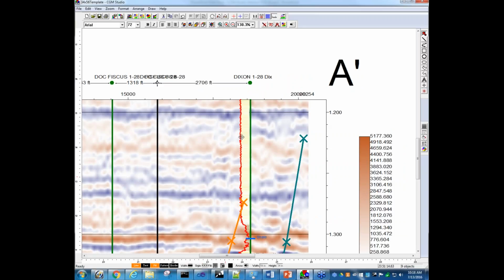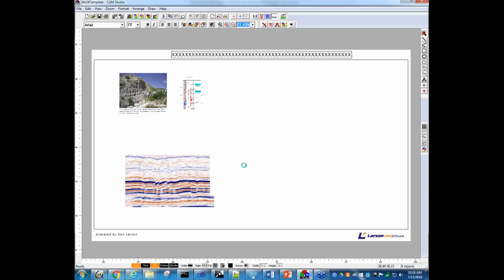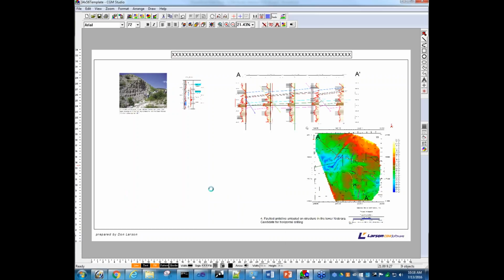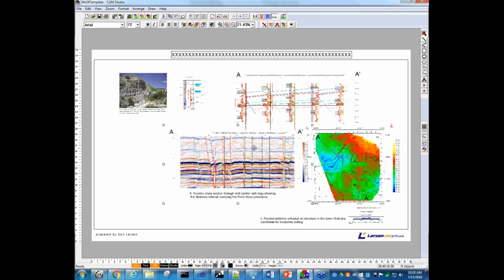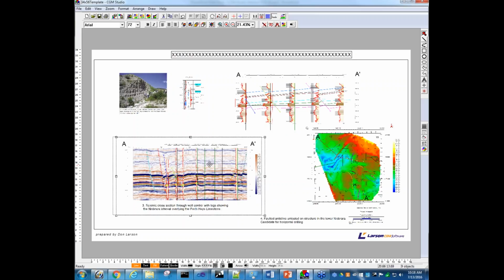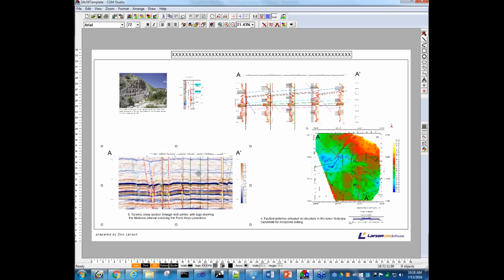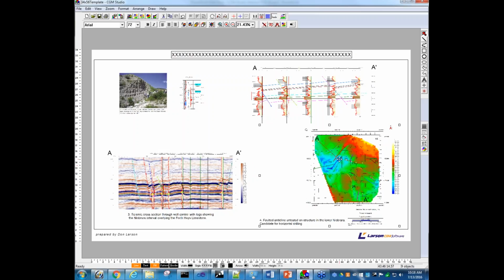You want to zoom in at high resolution. But if you're just working with layout, you don't want to continually redraw that. So that's why we have what we call the bitmap or the real mode. And so now when I move it or zoom or whatever, it's not redrawing. So that can make working with very large images much easier to do.